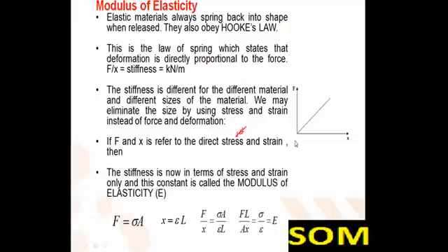We may eliminate the size by using stress and strain instead of force and deformation. As we know, force is sigma into area, and x is epsilon L. If we compute F by x, that is sigma A by epsilon L, which is known as Young's modulus of elasticity.